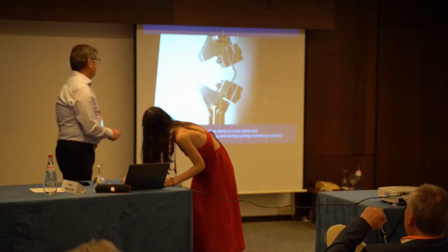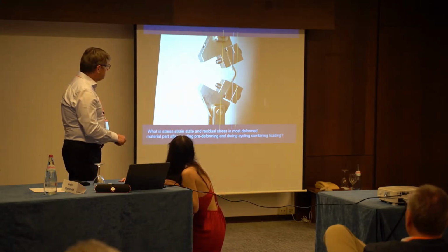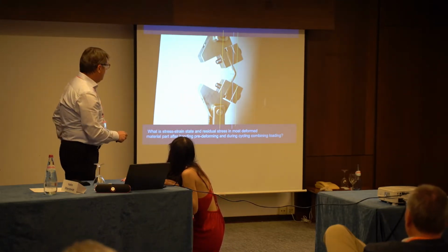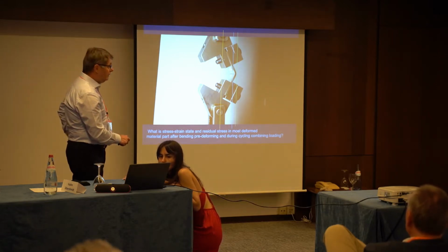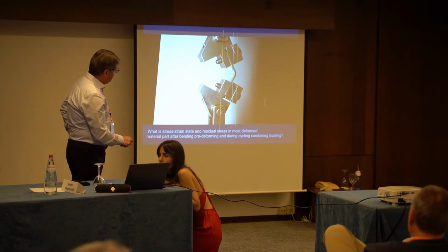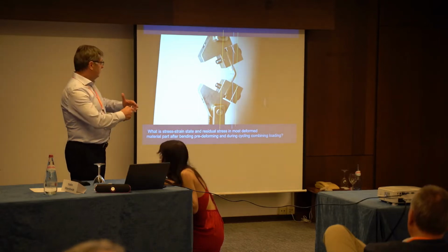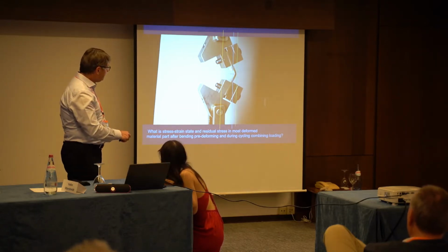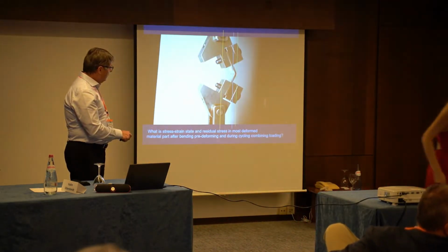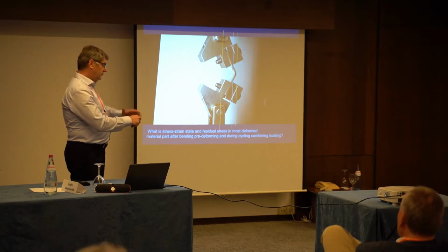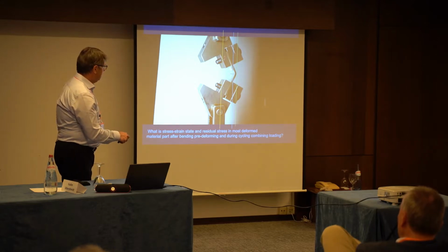So what happens? Of course, you have the tension and the bending at the same time. Here is the pin, so it's the spring for rotation. Additional tensile stress comes here, and this becomes a more critical region. Also, you change the geometry, because the movement from, for example, this green line on the tip to this blue line is a couple of millimeters, so it actually changed the geometry of the test.